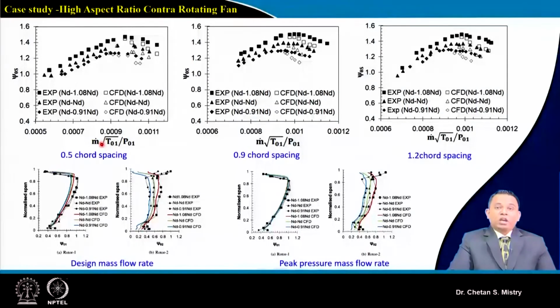But when we are doing our analysis or making both the rotors, then what needs to be the distance or axial spacing between these two rotors is very important. Basically that is what will decide your aerodynamic performance, your expected noise, as well as the length of your stage.